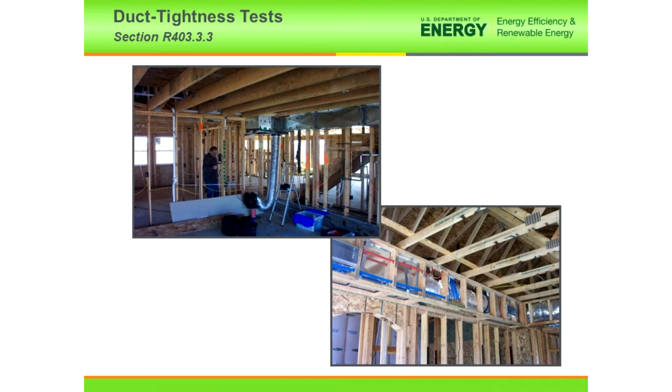And here's a picture of a duct tightness test at rough-in. You know, this is what these guys do. And if you guys were smart, this is where you would start, because then before you put the drywall up and all that stuff, you can catch those leaks in the system. It's going to cost you more money to go back and cut holes in places and seal stuff that could have been sealed at this particular point had you done a duct leakage test at rough-in, okay? Everything is still exposed.